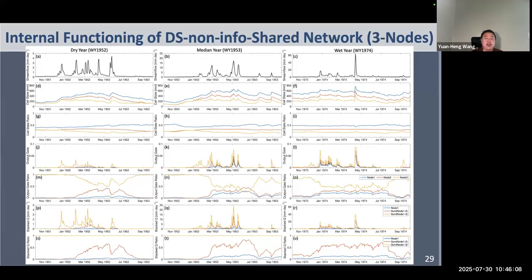And then you make your interpretation. Our interpretation here is that we have one surface flow path and two subsurface flow paths, and we interpret one of the subsurface flow paths as interflow, and the other as groundwater flow. But let me know if you have any better interpretation. We can come back to this slide if necessary.